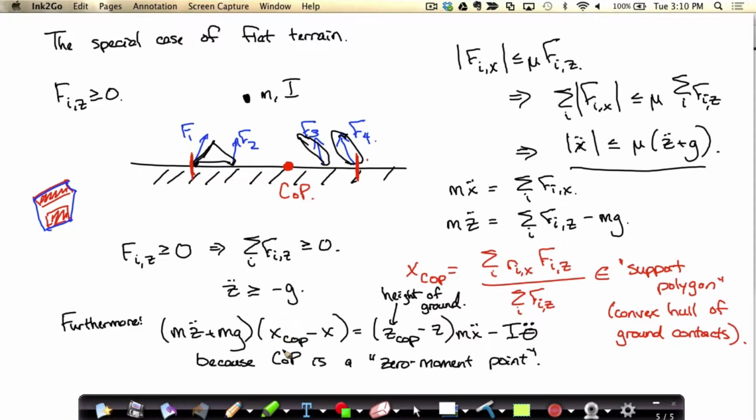All right, so now let's start using this to our advantage. One of the things we said that is a common assumption is to make z double dot equal to 0. Now remember there's a couple reasons to do that. One is that it simplifies the ground contact. It basically means you're not losing any energy into the ground. If my center of mass is never changing height, then I'm not gaining or restoring any vertical energy. So it simplifies contact, or justifies ignoring contact.